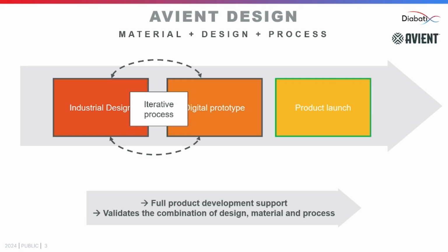And then with the digital prototypes, we are evaluating the design numerically with different materials that are selected from our portfolio. It can be either looking at the performance of the part with mechanical or thermal evaluation, as in the following case study, or looking at the process through injection molding evaluation.